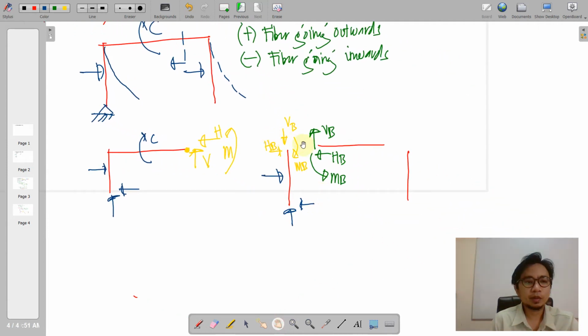Of course, we would want it to reflect all of the loading externally and then establish these internal forces. We place there the external force couple C, and then the three internal forces: moment, horizontal force, and the shear force. Okay, so again, this will transfer to this column here, the same magnitude but oppositely directed.